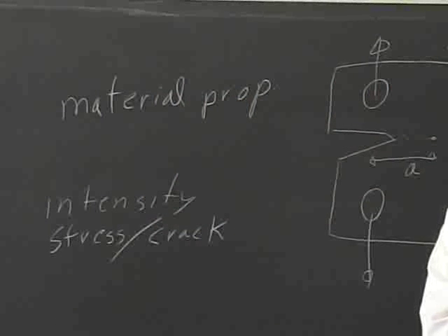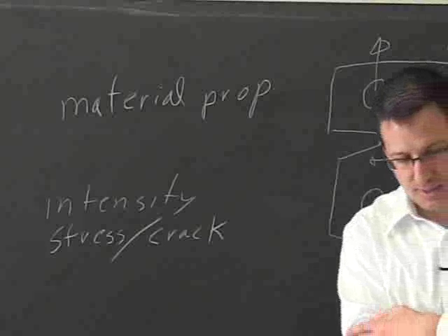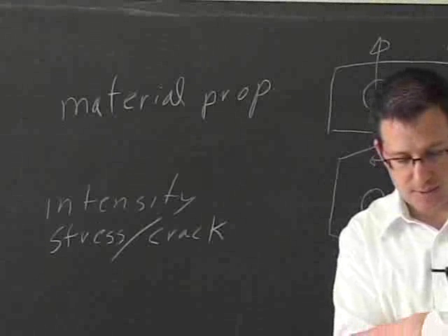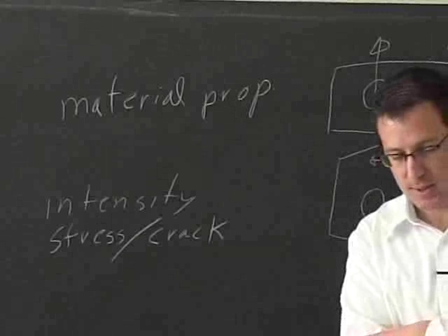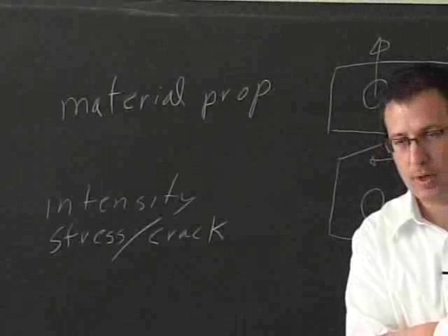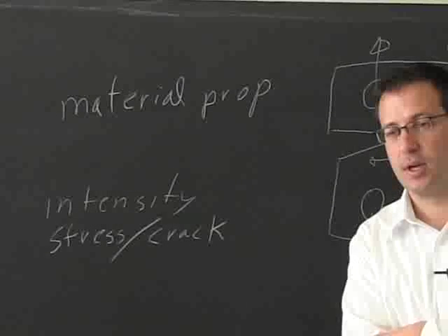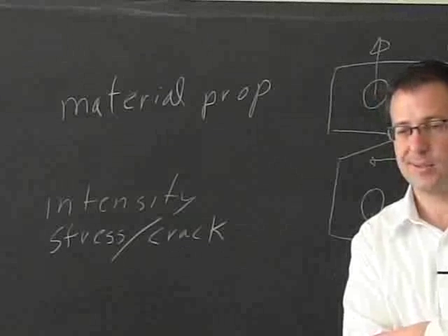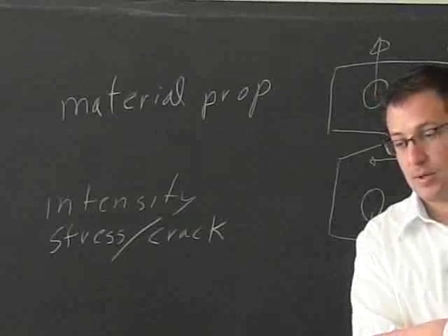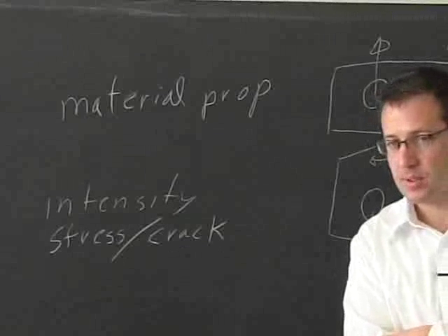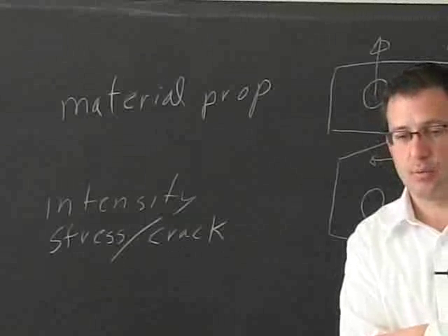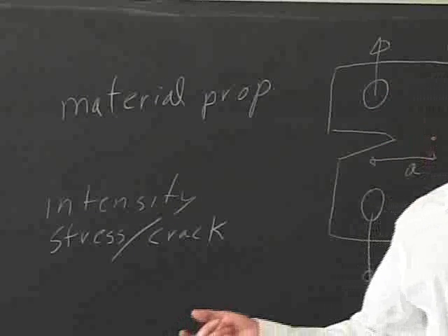So I want to evaluate my product for strength, and I'll give it a certain safety factor. And one way to do it is to load it. In this plot, this is a stress strain curve at a constant amplitude. Figure out how much time it takes to break. And you can do those tests on straight bars, but you can also do it on welded assemblies. It's actually a good way to reduce your